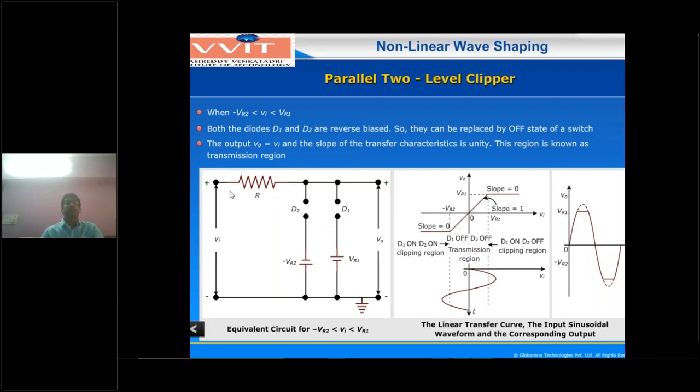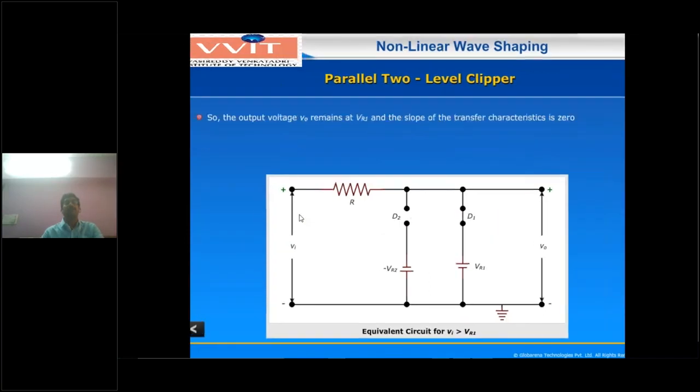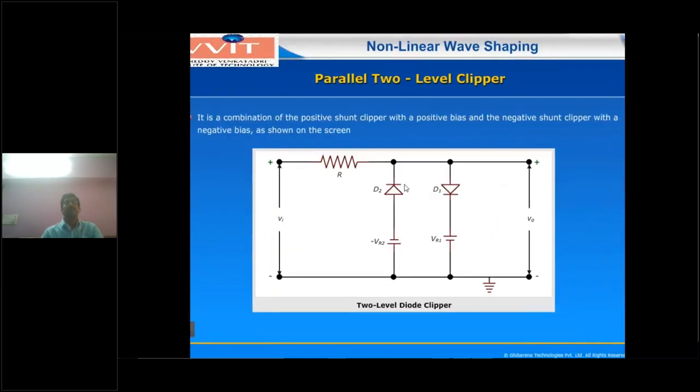First voltage. Now coming here, 2 volts is in the forward direction. Now diode D2 is in reverse bias direction. Here will be 2 volts, so here will be minus 2 volts. Now this minus 2 means less voltage compared to the cathode. The anode is at less voltage, so diode D2 will be in off condition.